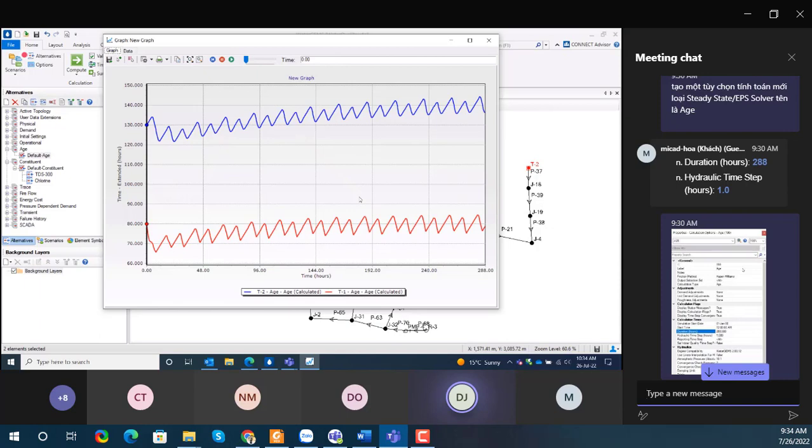So we've now settled out the initial calculation errors at the front here because of the other ages throughout the system, and you could go and update the rest of the ages throughout the system with these settled values if you wanted to get it perfect. But it's certainly giving you a very good indication of how old the water is in those two tanks, and you can see why the chlorine residual coming out of the tanks is so low when it takes 140 hours to turn over.